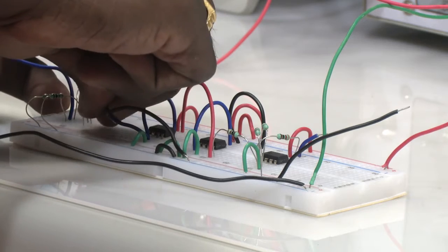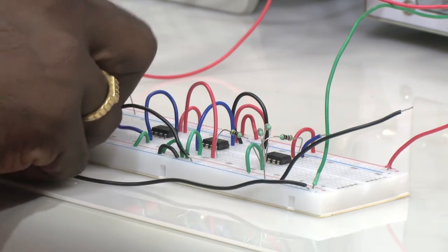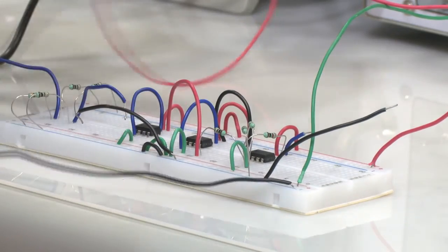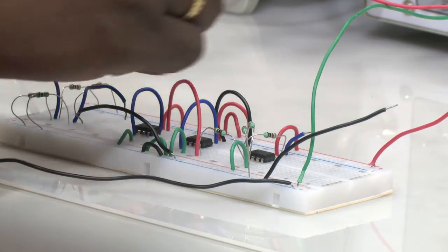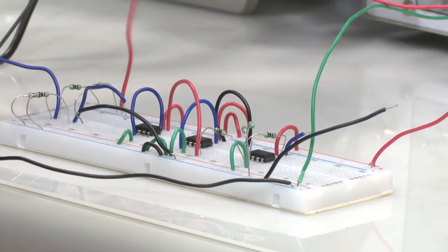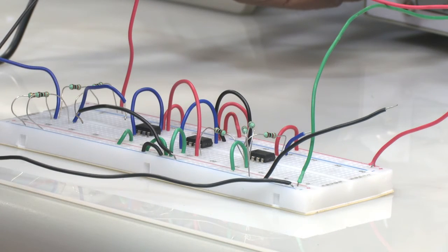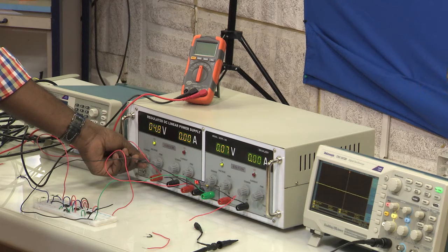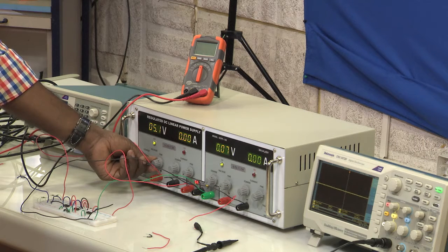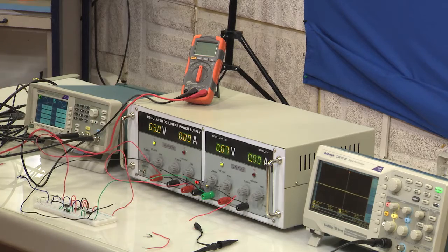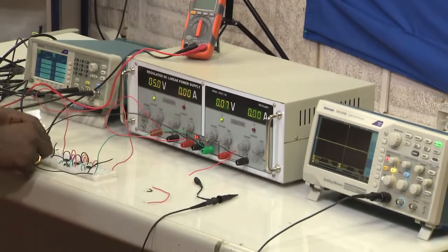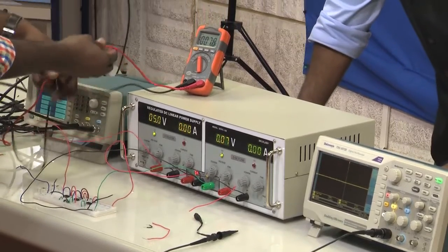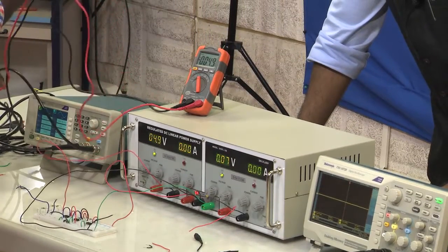So, if you see again what he is trying to connect, he is trying to connect the Wheatstone bridge with the supply voltage, and we should expect the output to be 0 volts. So, he is applying a supply voltage across the Wheatstone bridge, and you can see here the voltage is about 5 volts, okay, and then he has to measure the voltage at the output of the Wheatstone bridge, and the voltage should be close to 0.